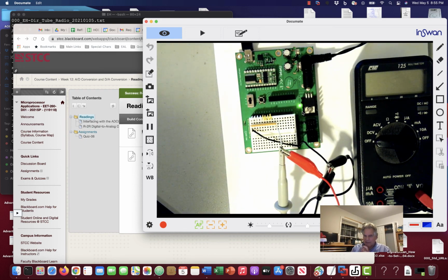But basically, a digital to analog converter is a box where you put in a vector of signals that, for example, maybe go either 0 or 5 volts. And out the other side comes a voltage that is proportionally somewhere between a minimum voltage and a maximum voltage.